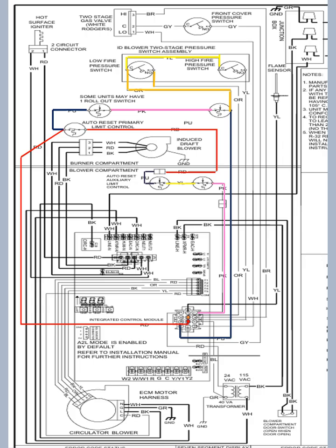The control module performs a gas valve circuitry check. To verify gas valve relay state, both the first and second stage relays on the board will be open, and there will be no voltage at the gas valve. Even if the gas valve relays were closed, you still would not measure voltage at the gas valve because the front cover pressure switch that breaks the common wire is open, so there's no complete circuit to open the valve.